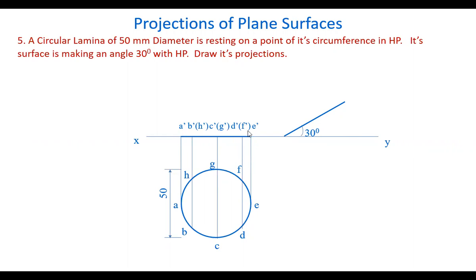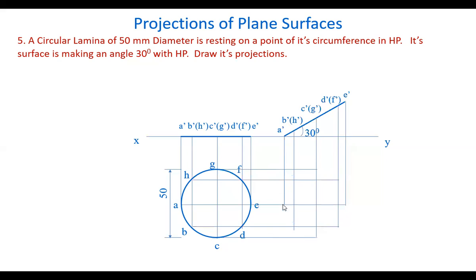Now, mark these points here on this. All the points are marked without any change. Now, to get the final front view, draw projectors from all these points and draw horizontal lines from these points. Get the intersection points here. All the intersection points A, B, C, D, E, F, G, H up to H. Mark the corresponding points carefully, as there is a possibility of committing a mistake. So be careful. A dash here, projector, and a horizontal line at A. This is the intersection point here.